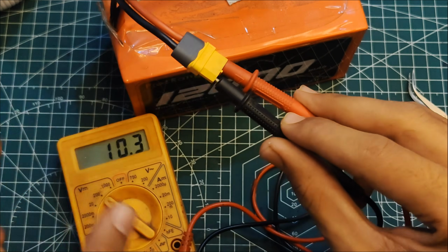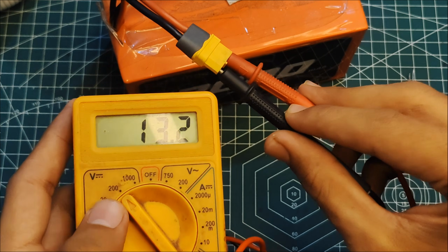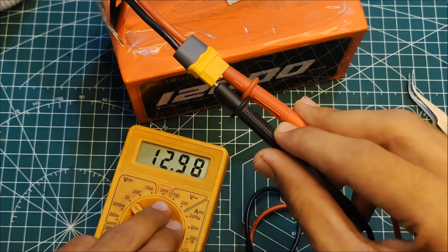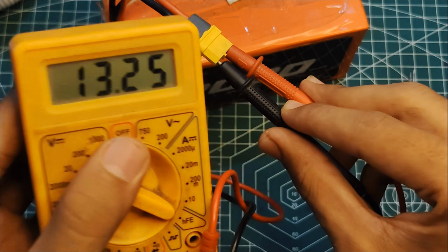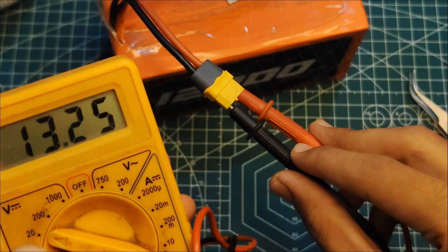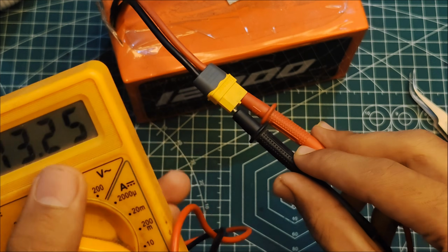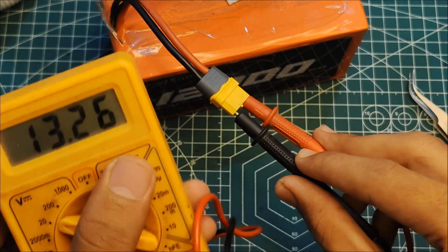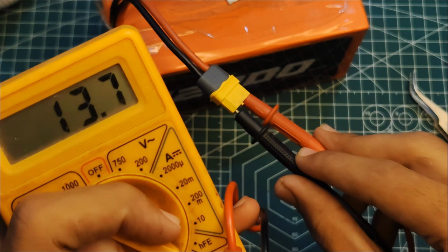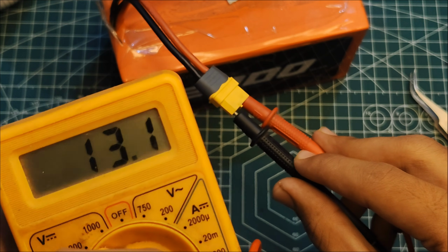So here you would be getting a value of 13.2 volt, and I have set it to 200. You can set it to a lower one, but this sets a range for the amount of voltage that you want to measure here. So as I put it up to 20, you can see 13.25. So the resolution is also increasing with it. And as I put it onto 200, you could see the resolution, or the number of decimals, reduced.